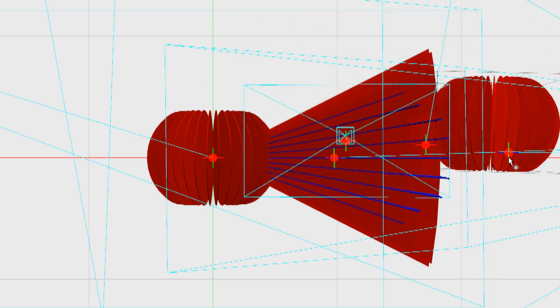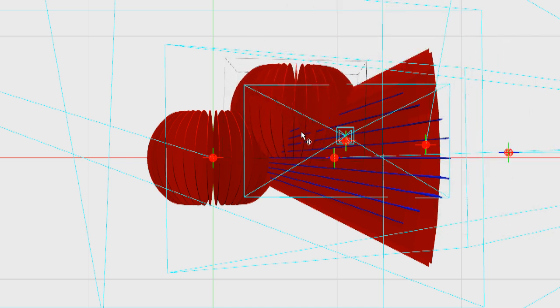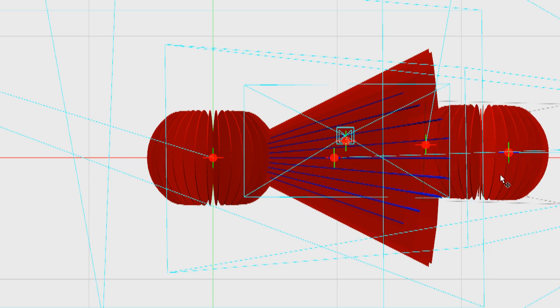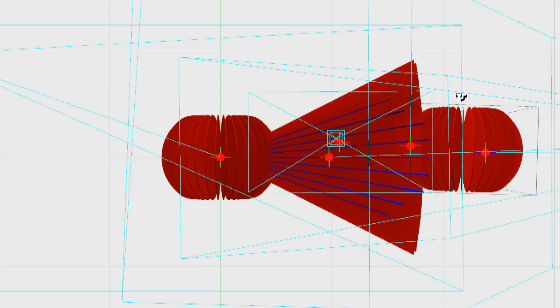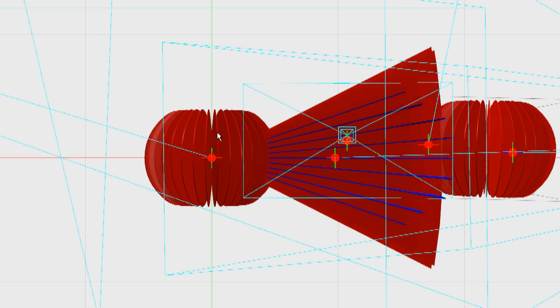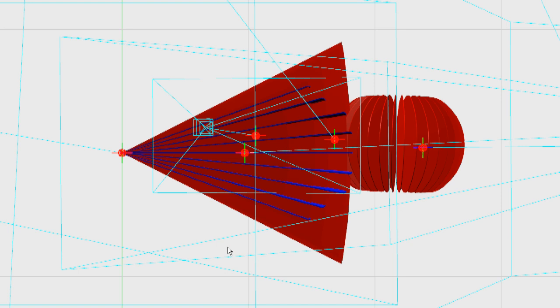However, with a diversity receiver, because it's a higher gain, 11 decibel, versus 2 decibel of the rubber ducky, we can get right the way out here. So not only do we get a greater range, but we also have a more consistent signal, because regardless of our orientation on the plane, whether it's vertically or horizontally, the diversity antenna will be able to pick up a good signal. So that's your typical diversity antenna, 11 dB pattern.